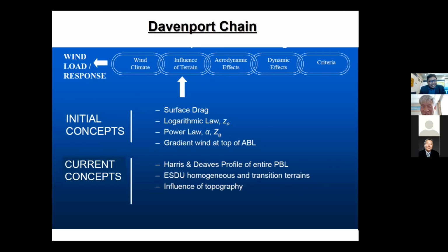As Professor Cao said, the Architectural Institute of Japan, AIJ, has published a recommendation on wind load evaluation. In that document, they allow CFD application for evaluation of wind load and wind pressure, but only under very limited conditions. And in that situation, the wind tunnel test may be easier than CFD. But this is just a recommendation from the academic field.